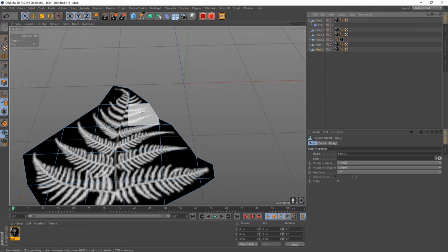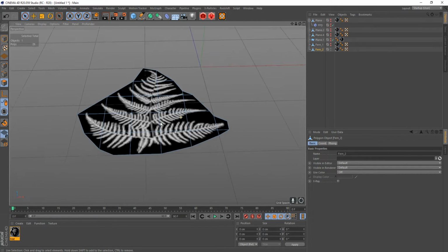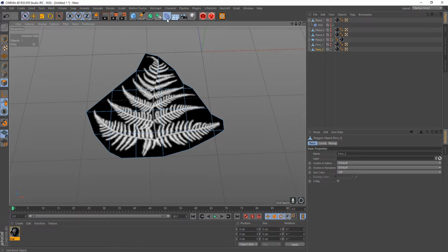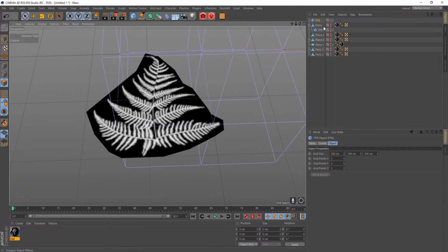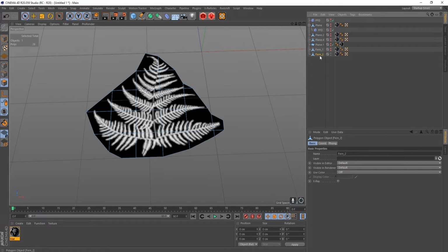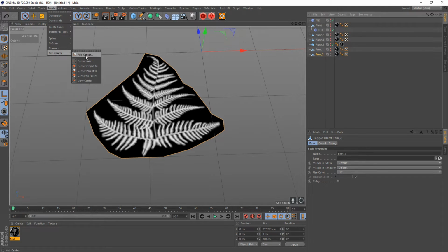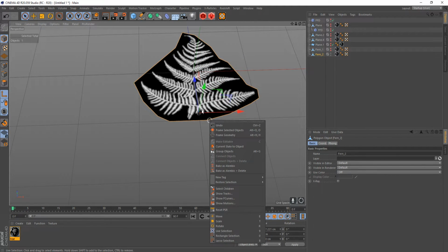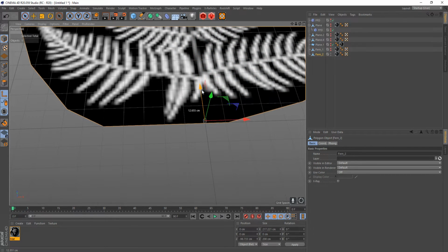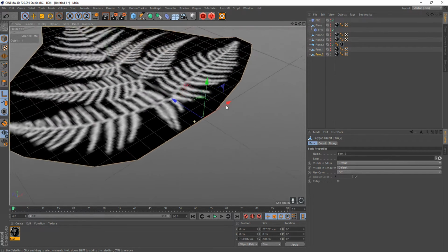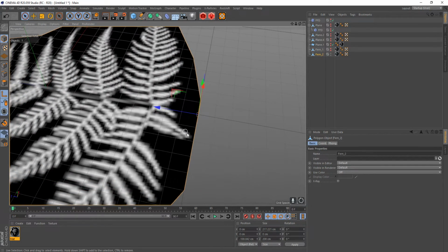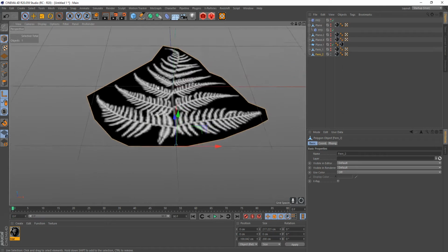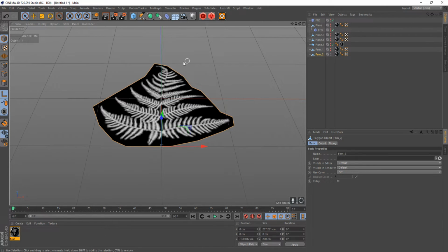and I'm going to make it viewable. So that looks pretty decent. Let's just add another FFD in here. And actually, before we do that, again, I forgot to center our axis. Back into object mode, enable our pivot edit, and then we go to axis center, center object 2, and then let's set this at the bottom this time because we got a little bit hanging over. I'm not sure how that's going to affect where it's at in Speedtree. So let's just leave it like that.